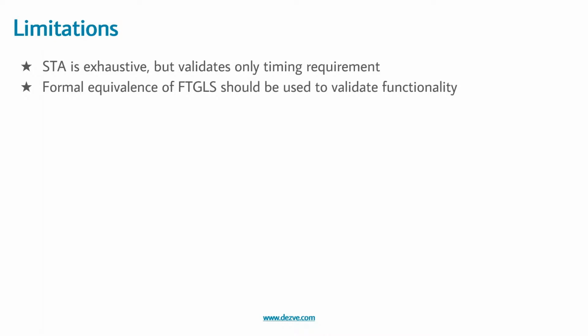Now for timing improvement, there can be scenarios where the tool wants to move a register, like retiming or pipelining. These are advanced concepts. The tool can change the timing behavior if a path is not able to meet timing and the previous path has a lot of slack, it might try to move a flop so that some combinational logic can be reshuffled between these paths.